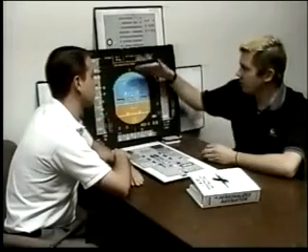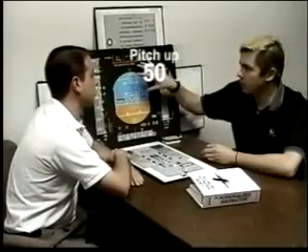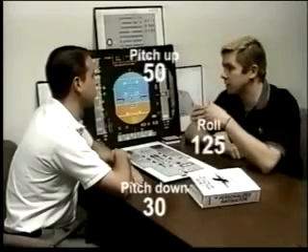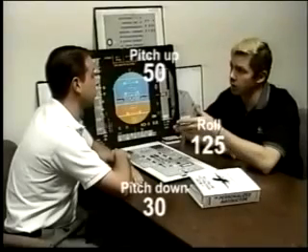And what kind of parameters would you have to exceed to get into abnormal attitude law? Well, an easy rule of thumb is just double whatever your maximums are. For instance, our pitch up, we said it was 30, 25, 20. 25 is the mean in there, so just double that, 50. Pitch down, we said it was 15, double it, it's 30. Roll, 67 degrees, double it, that's roughly 125.